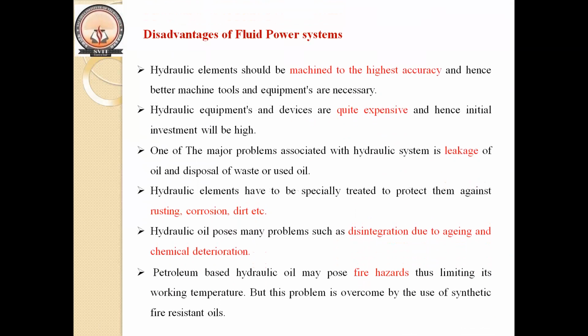Then we have disadvantages of fluid power system. The first disadvantage is leakage is one of the main problems in fluid power system. In order to overcome the problem, hydraulic elements should be machined to the highest accuracy, and hence better machine tools and equipments are necessary.